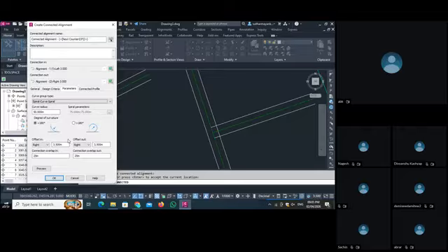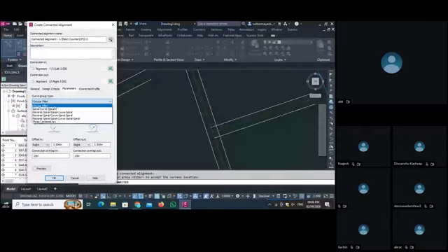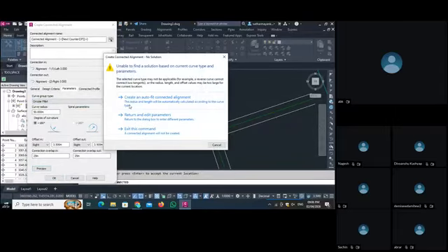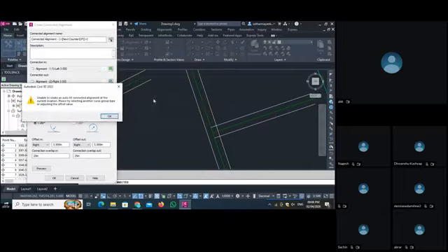So whatever we have, as it is, I select and do the preview. See, in our curve group type, we select the circular fillet as this is the best fit option here. You can select any style you want. Now I give the preview, so it will create the connected alignment, yes.